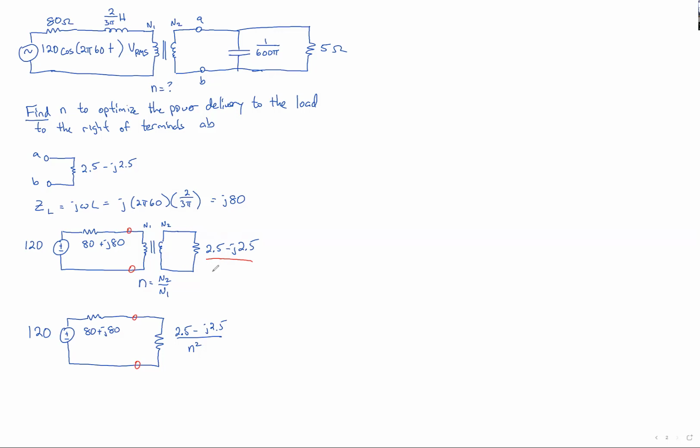And the answer is that although we're destroying the internal currents and voltages, if this is an ideal transformer, we have not altered the power that's being dissipated by this, only the currents and the voltages. So this entire circuit still is an accurate representation of how much power is delivered by the source, how much power is absorbed by the source load that's somehow built into the Thevenin equivalent of the source, and how much power is delivered to and absorbed by the load.